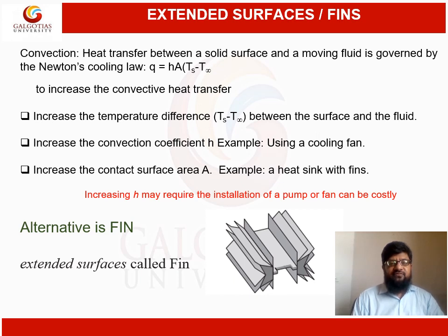Another way to increase the heat transfer is to increase the convection coefficient, for example, using some external fan to improve the convection. Another is to increase the overall contact surface area with the fluid. Fins fall in that category.